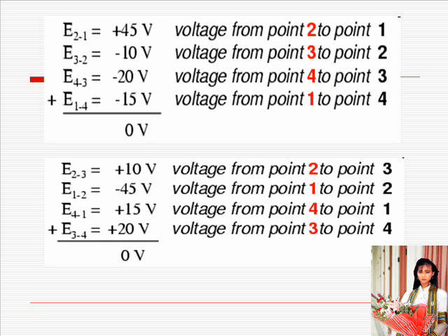We should already be familiar with the general principle for series circuits stating that individual voltage drops add up to the total applied voltage. But measuring voltage drops in this manner and paying attention to the polarity mathematical sign of the readings reveals another facet of this principle, that the voltages measured as such all add up to 0.